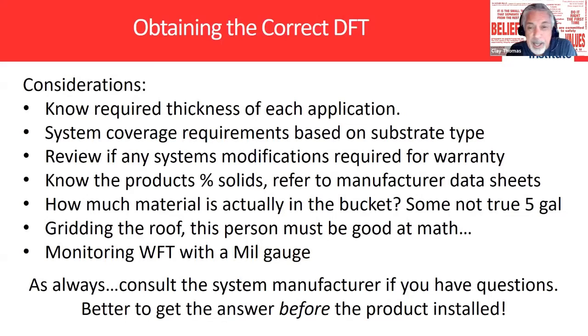You want to know what the percent solids is. That's on the manufacturer data sheet: how much material is actually in the bucket. We talked about that, and the Tremco Alpha Guard specifically, when I was looking at the two data sheets.